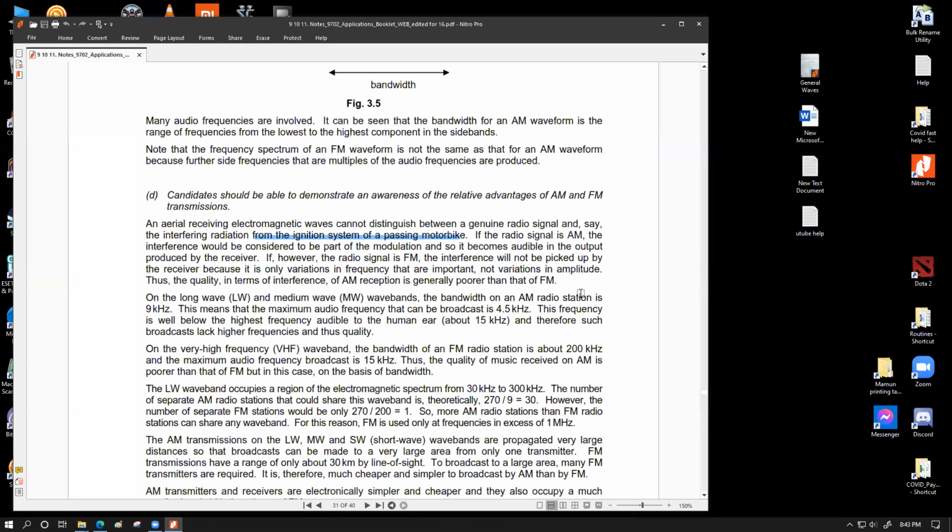It means AM signals are more prone to picking up noise in the communication pathway, and they are likely to give us a more noisy output. Whereas frequency modulated waves don't have that property because of the inherent structure, because they're handled with the variation of frequency change, so amplitude variation does not pose any problem.